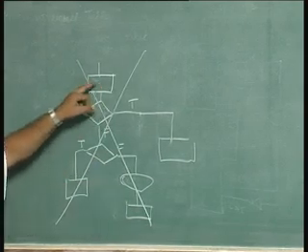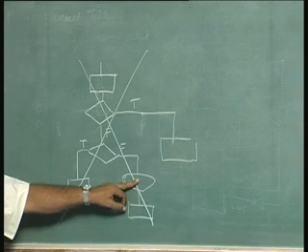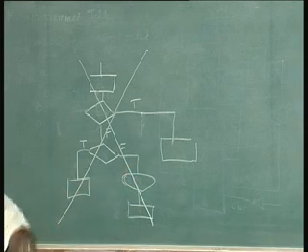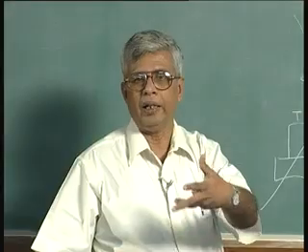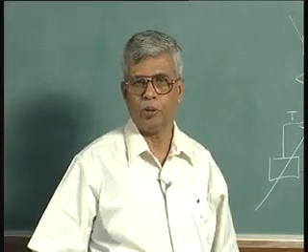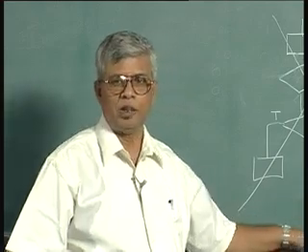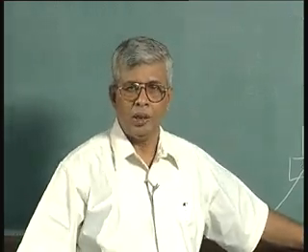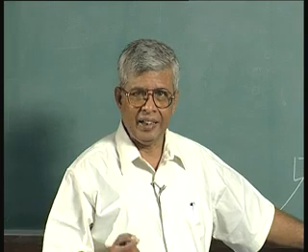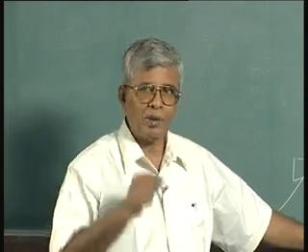In state 1, if this is false and this is false, this output is generated and then it goes to state 3 or whatever. That conditional output has no place in a microprogram approach. So, all conditional output boxes have to be replaced by output boxes. So, in effect we are increasing the number of states.